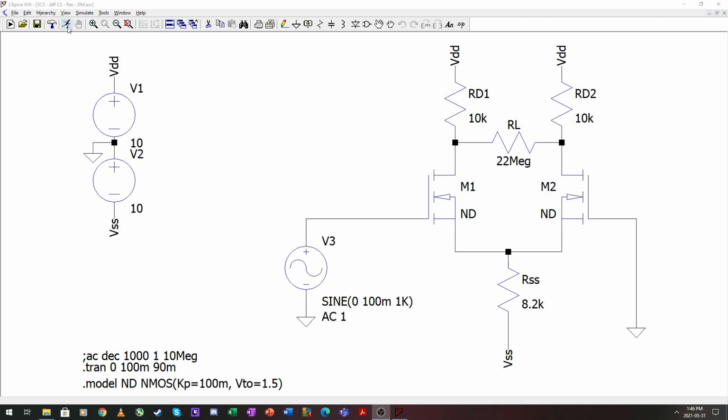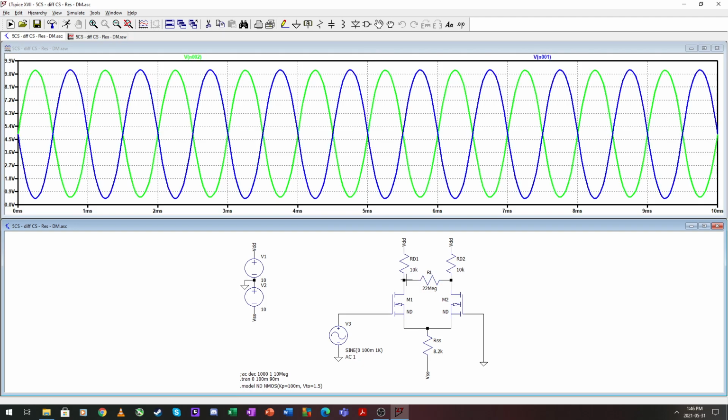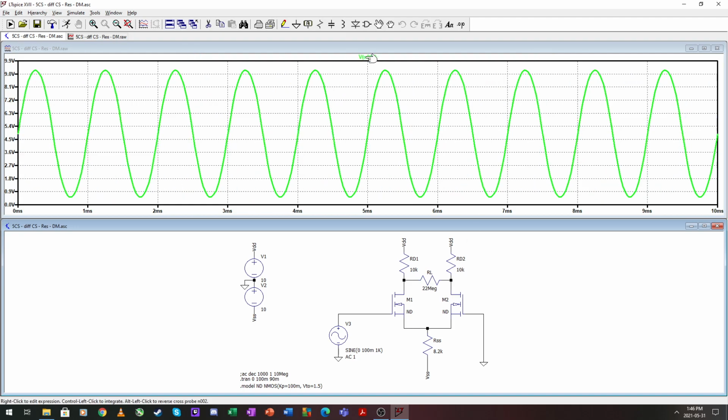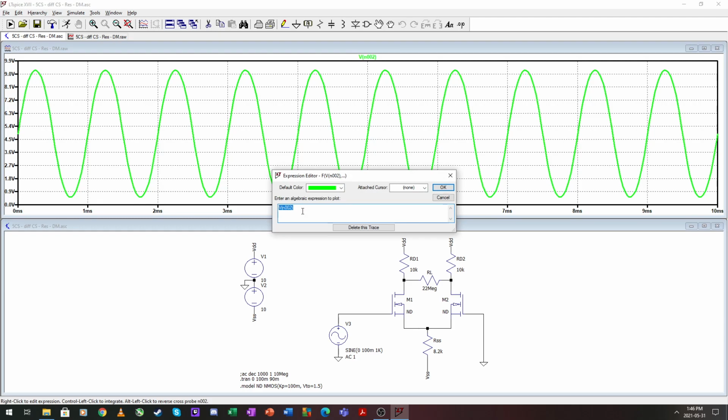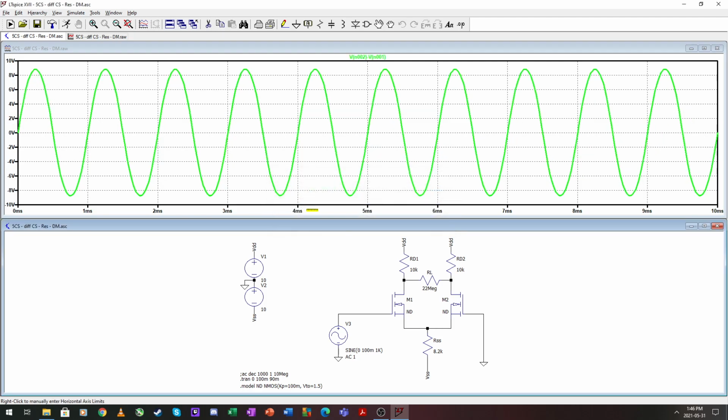Okay, let's have a look at the differential mode with a resistor. If we run this, note that everything is exactly the same as it was. So when you're doing fully differential, using a resistor bias is not a problem. There is our output. Our gain dropped a little bit, but I think that is due to this no longer being a current source but an E12 resistor. So yes, we can still get fully differential using a resistor like this.